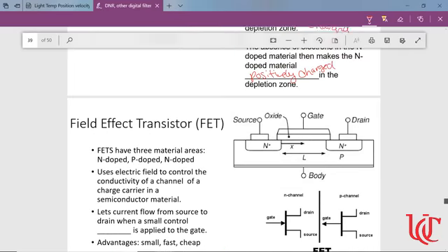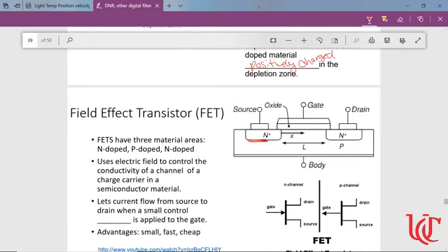How that transistor works is, again, anywhere they interact, I'm going to get a depletion zone build up, where I get positive charges on the n-type, negative charges on the p-type. And normally, again, those charges are going to repel further electrical current through that.